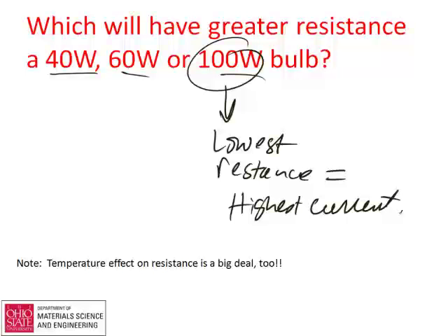And you can measure that, and if you do Ohm's law with it, you'll actually find that the light bulb initially has a huge inrush of current, and then once it heats up, its resistance rises a little bit. This is why often when you turn a light bulb on, that's when it will burn out. There's that huge inrush of current, it thermally shocks the bulb, and then the light bulb ends up burning out. So that's one thing that you can do.